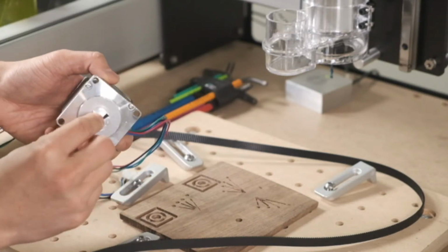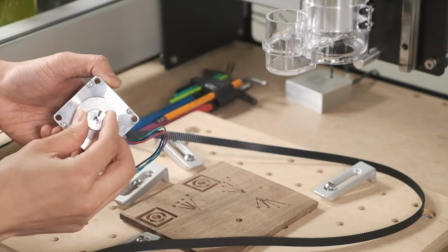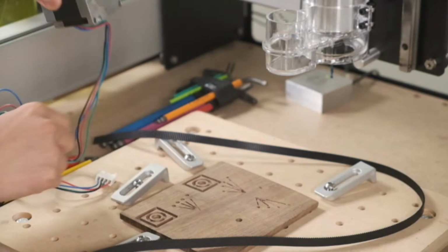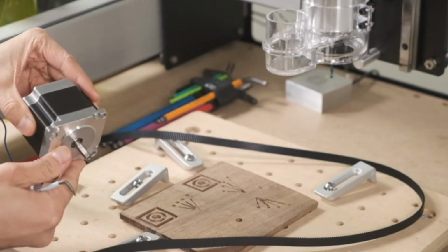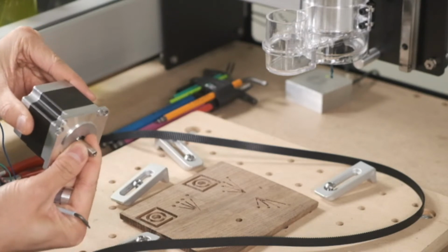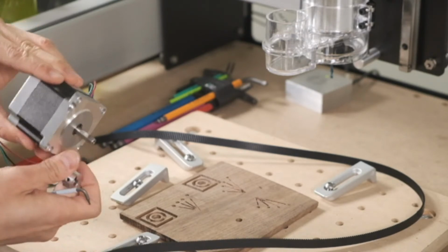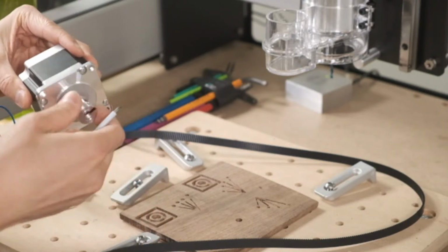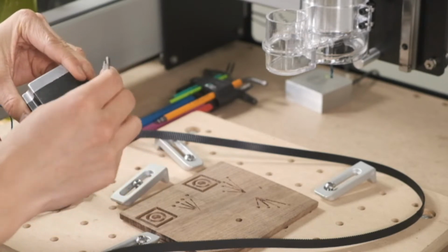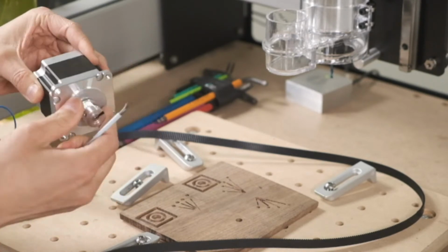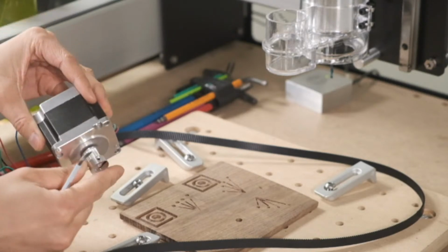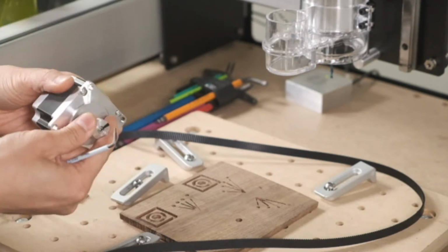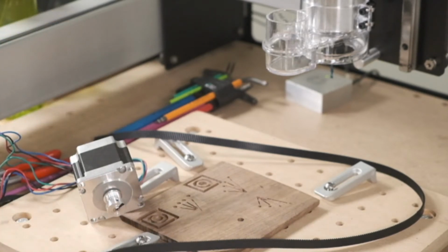Here I've marked them in Sharpie just to make sure that they move in sync, and they don't. When you tighten these set screws, make sure that, I don't know how well you can see this on the camera, but there is a flat on that stepper motor shaft. So one of your pulley set screws, make sure that's over that flat, because that'll help index and key it and lock it in and make sure these two rotate synchronously. So pulley to stepper motor is probably the first place you should look. This happens a lot on the belt drive.